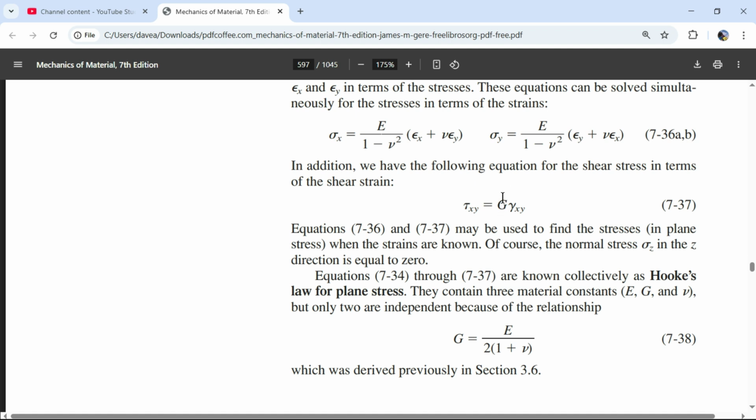And so that's where we get this value. I'm sorry, this is going to be like 29,000 for the shear stress. This is like 0.004, I thought. And then this is the number, about 10 million, that relates those. Obviously, 10 million times 0.004 is not quite right. So maybe this number is closer to 40,000. And maybe in some books, shear stress for steel can be higher than half. Maybe it can be up to 60%. Cool, all right, but anyway.